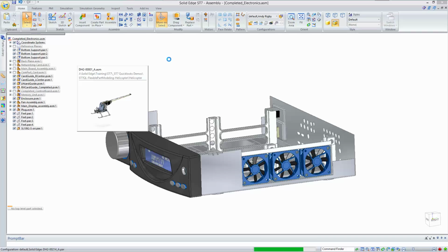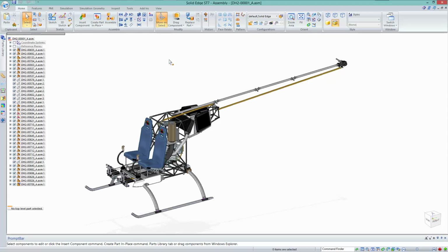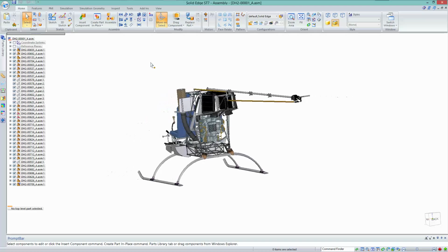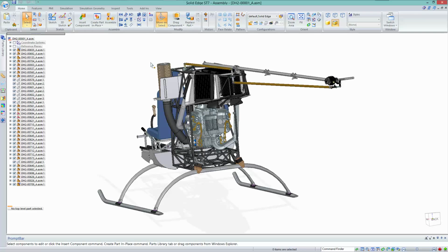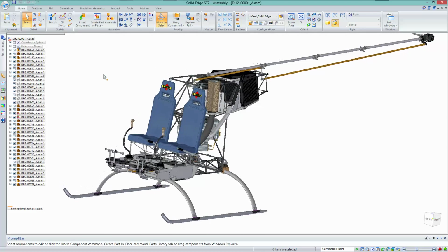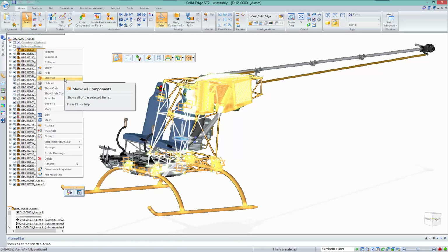You can see the green progress bar at the bottom there, so there are a number of controls in Solid Edge you can use to help load. If you're working with larger assemblies, then you've got some really useful controls to define how much information is loaded when you're opening up an assembly, how many of the components are displayed, and you can set that up to work kind of as last saved, or you can get Solid Edge to work off the number of components in an assembly. So a lot of useful tools for defining how long it takes and what nature an assembly open operation takes. Okay. So let's have a look at a second approach that we can take to designing in context.